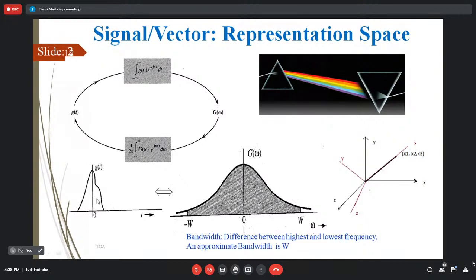In order to answer this question, to see what its frequency content is, how much frequency I need to retain for its transmission bandwidth to be determined, or how the signal energy is contained, up to what frequency range I have to consider, that answer is obtained by doing Fourier transformation. So g(t), as if it is an object, multiplied by e to the power minus j omega t.